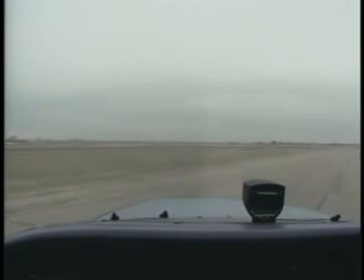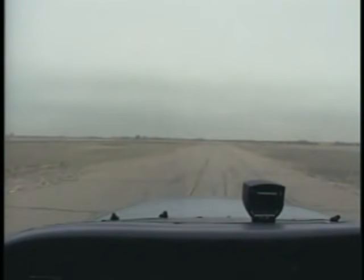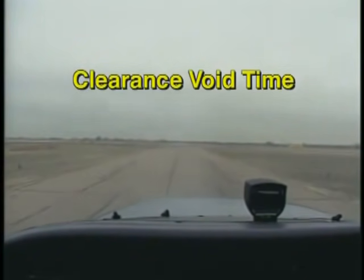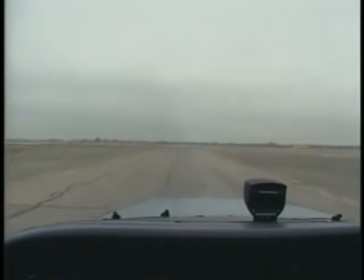When departing an airport without an operating control tower, some additional procedures may apply. For example, you might use a ground communications outlet. You may be issued a clearance void time. ATC uses this procedure to reserve airspace around the airport. If you do not depart before this time, your clearance will be canceled.